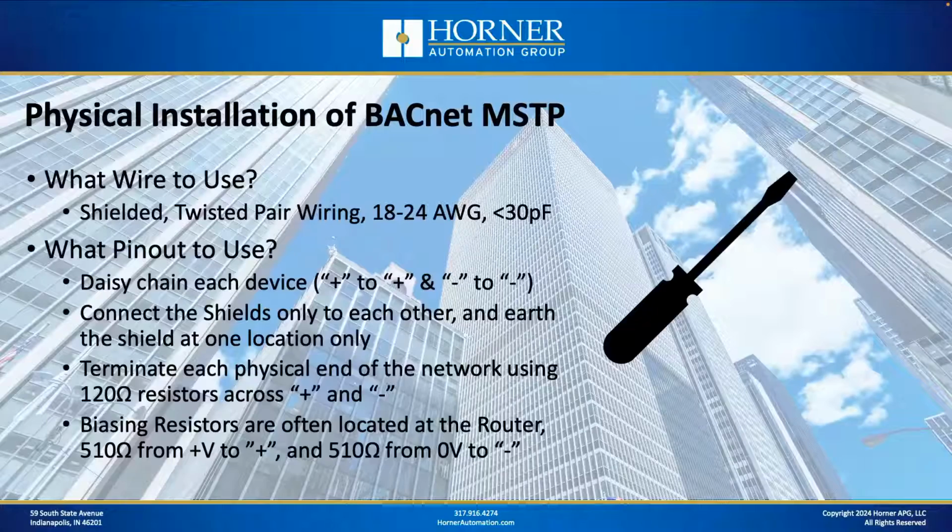At one point in that continuous shield, you should earth the shield, again, at one point only, and that'll provide an appropriate way of shunting any noise and keeping it away from the transmission signals.